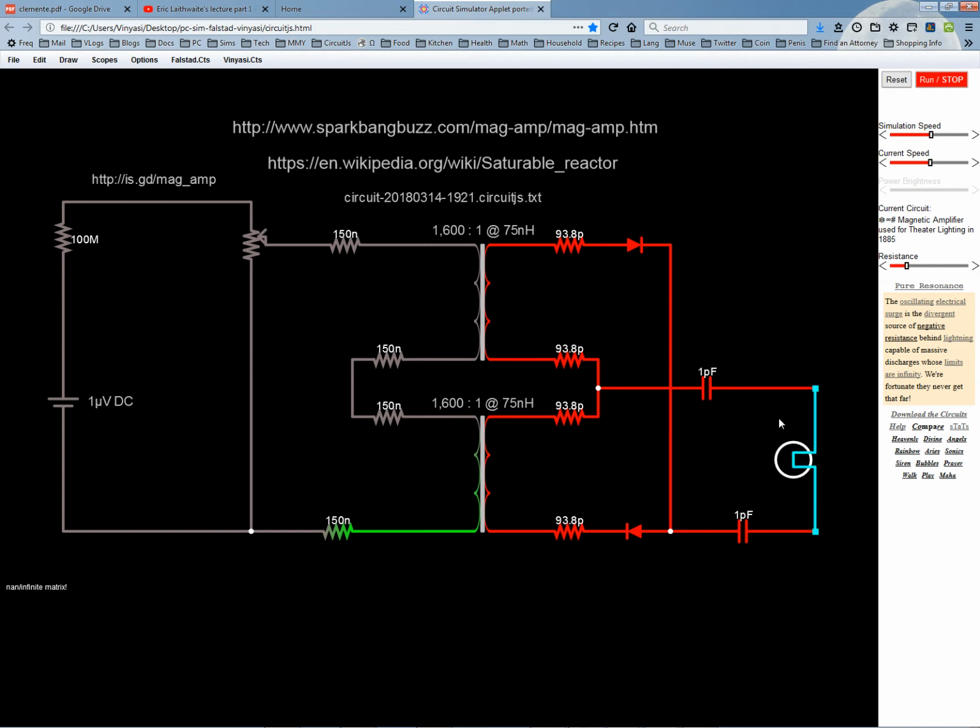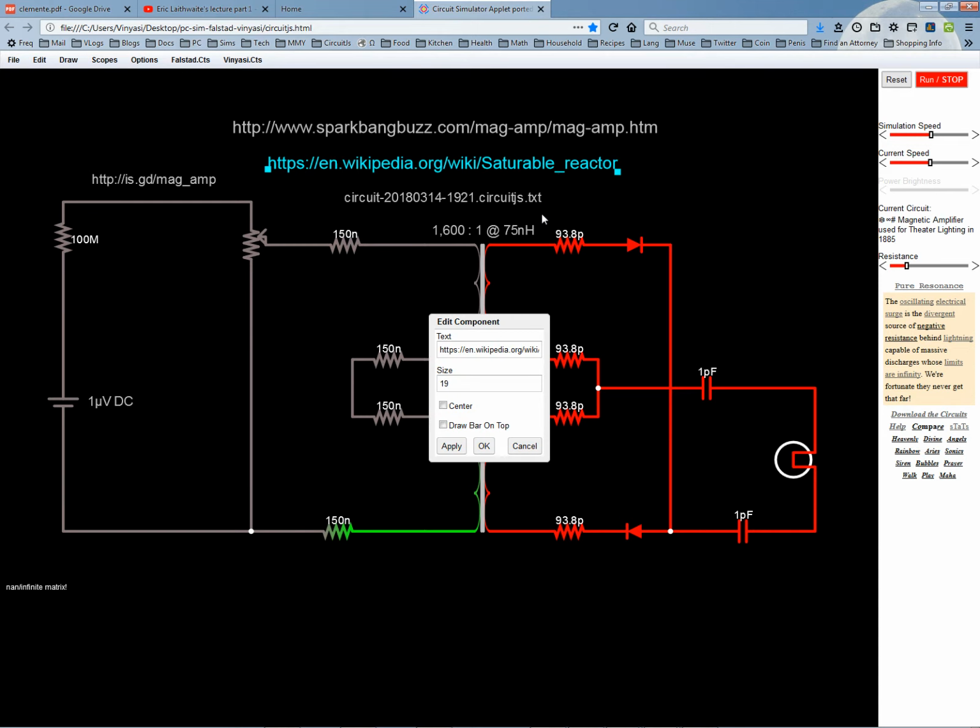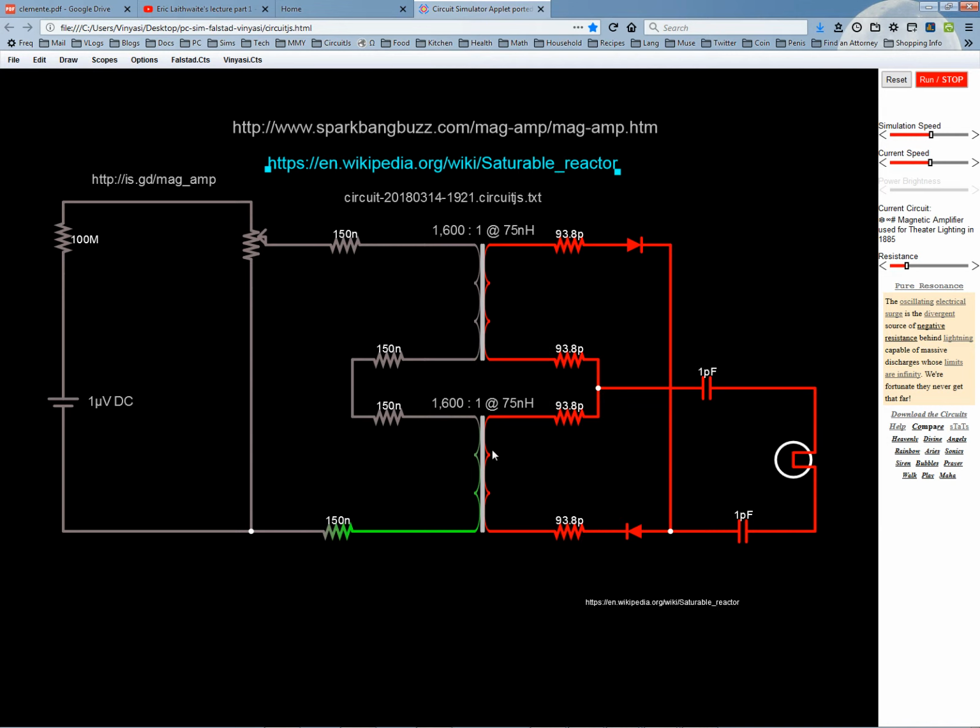Here, I actually light up these wires and this side of the resistor, so it shows it had a chance to put some power in. The way we find out how much power is in: we pick a component, it doesn't matter, it can even be the text, and open up its edit dialog box, then save it by hitting OK. That erases the error, the frozen condition, and now we can put our cursor over any component and see what's accumulated there.